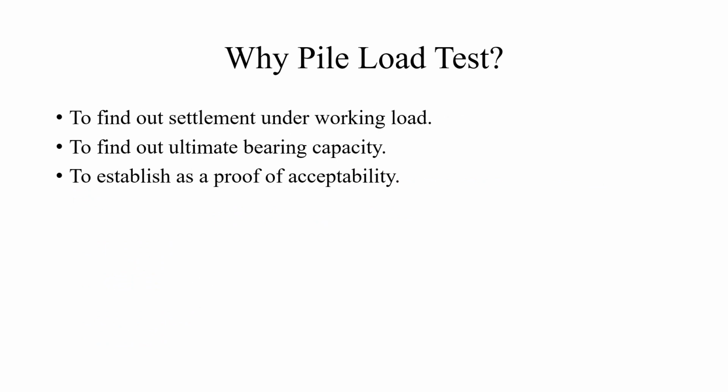Before we start the test, why do we have to do the pile load test? Pile load test is used to find out the settlement under working load. That is, once the building has been completely constructed, we have to find out whether it will settle and how much it will settle if the building comes up. Another thing is to find out the maximum bearing capacity of the pile, that is, the maximum load it can carry even in the extreme cases, and to establish a proof of acceptability.